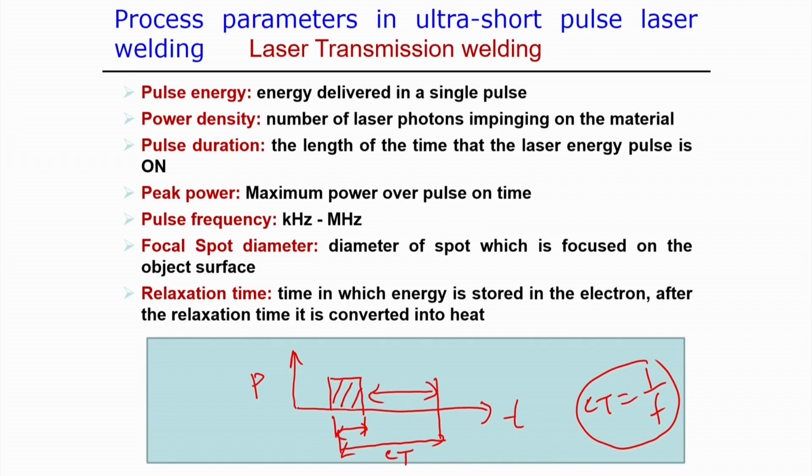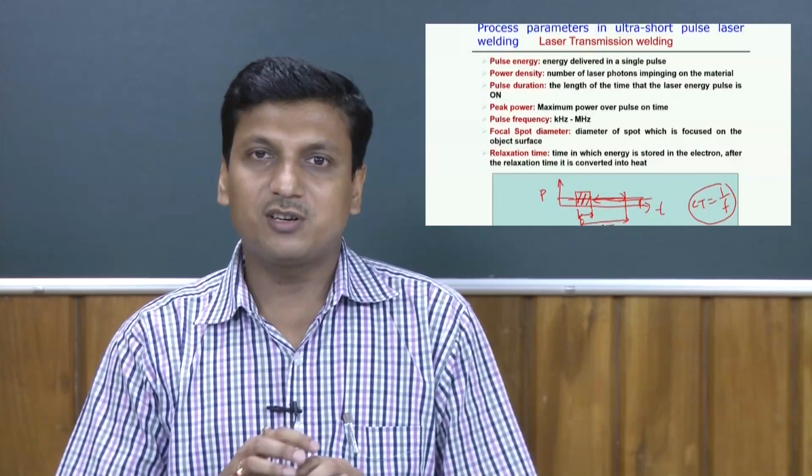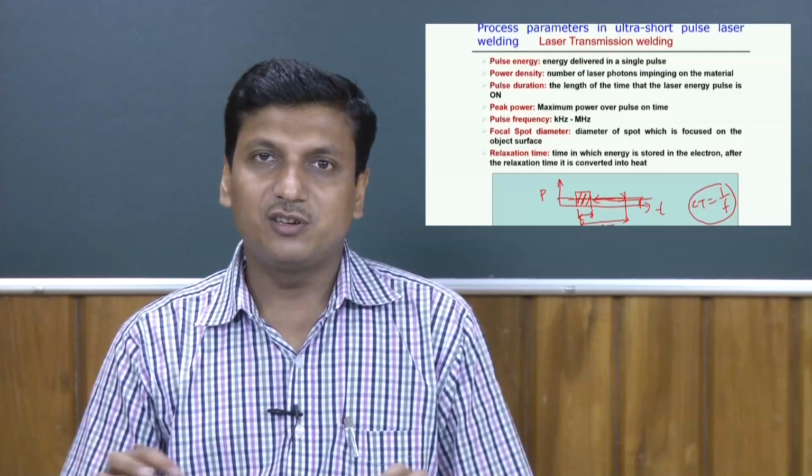These are the typical pulses we generally use in the laser welding process. Here we are assuming a rectangular shape, but the shape can be different. Sometimes we also use the average power, which lies between the peak power and the base power. This average power is simply a representation of some constant power over the duration of the welding process.